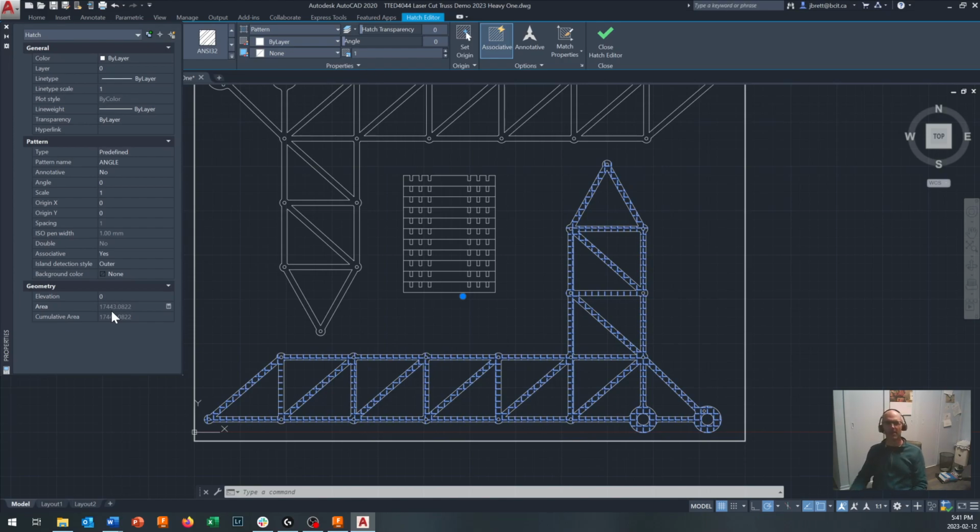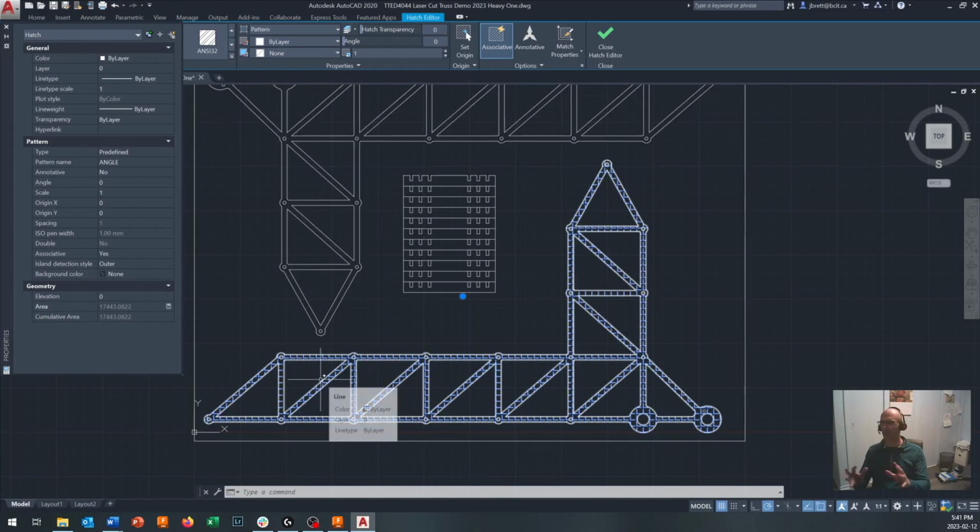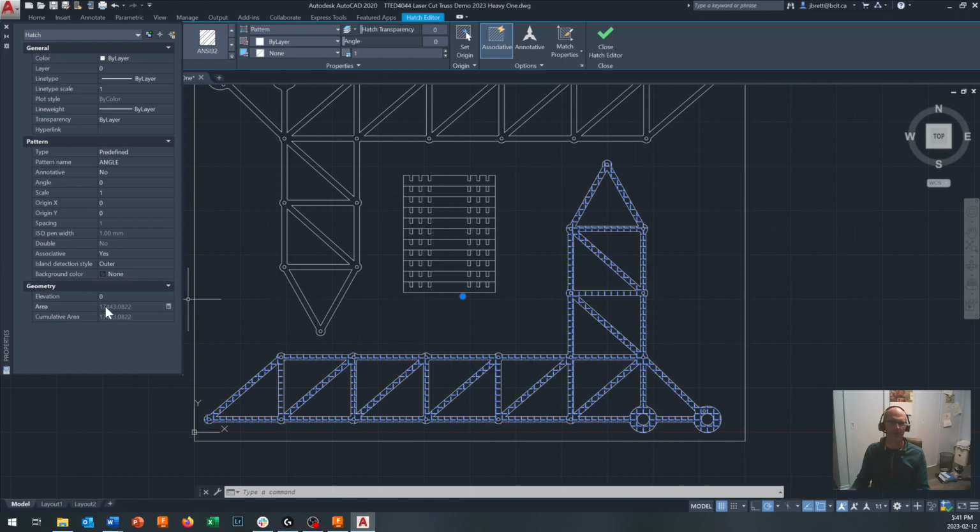And of course, if you've got the cross section, you know that you're cutting it from 3mm thick material. So this is going to be the dimension in square millimeters. So you've got 17,000 square millimeters. Multiply that by 3mm. That gets you the volume of that cross section. Okay, multiply that by 2 because you've got the 2 cross sections. And then go ahead and just multiply that by the density of the hardboard that we're going to be using, which is somewhere around 0.9, which we'll get to in just a moment.